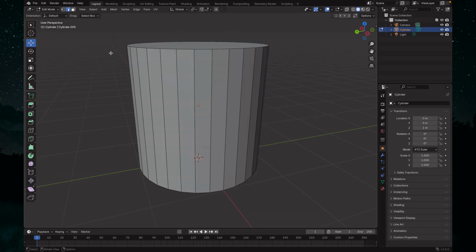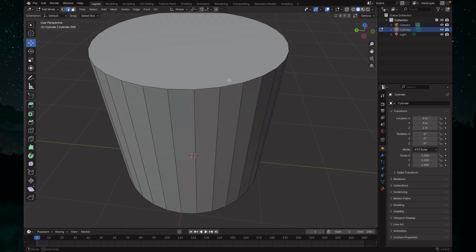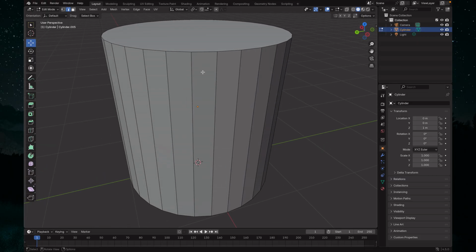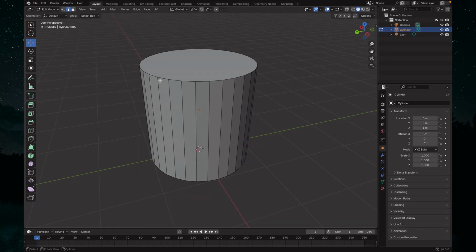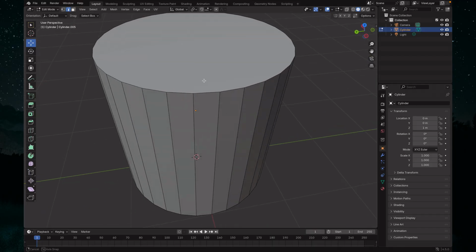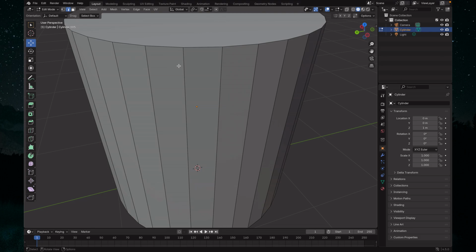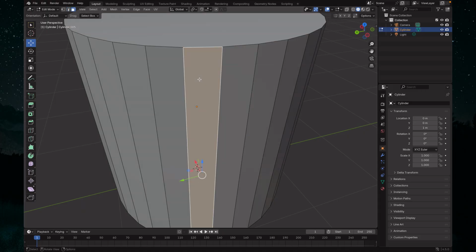So now if we click on the side, you can see that our edges now have been highlighted by black. It shows you that you can edit every component on this object you are seeing. So now in editing mode, what helps us to edit are three things. There's what we call vertices, or a vertex. This is a vertex, and we have what we call edges. These ones I'm highlighting are edges, and we have what we call faces. These ones you are seeing right now are faces.